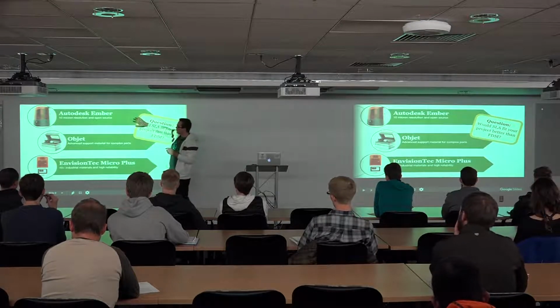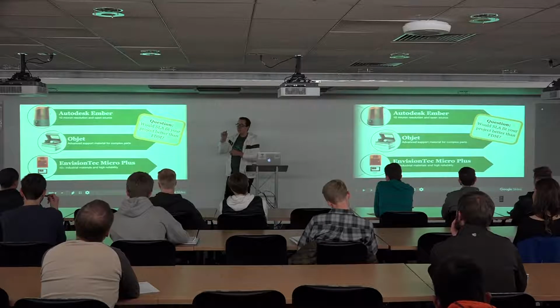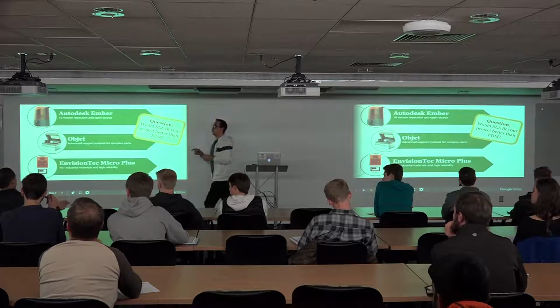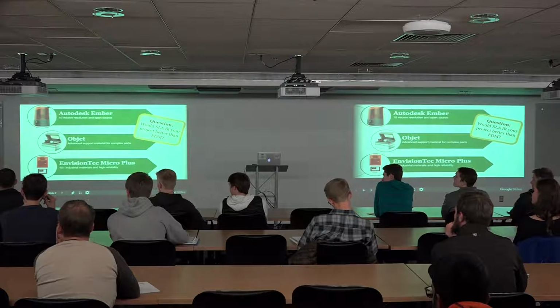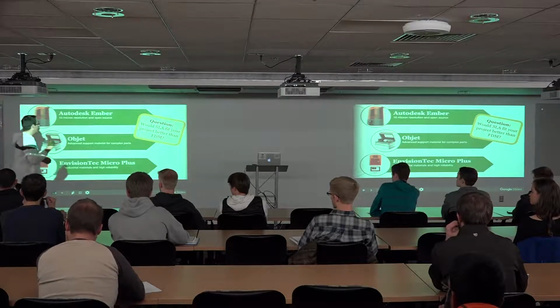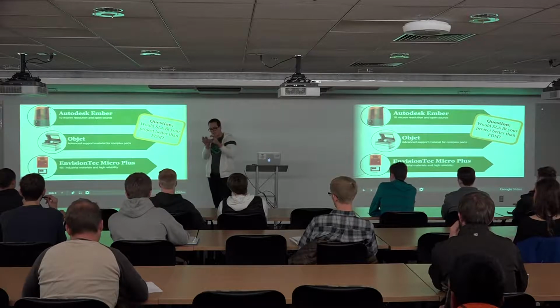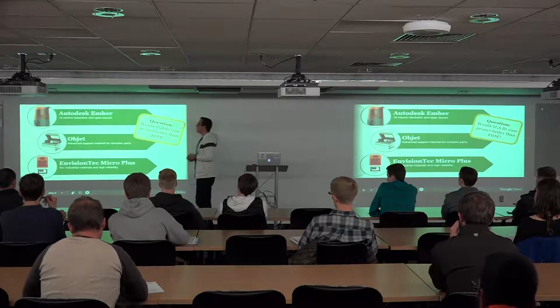So the Ember is also an open source printer, which is really cool. And it prints down to 10 micron layer thickness, so you can get some really, really neat detail. Did you bring any of those parts? Oh, did they pass this one around already? So yeah, this is an SLA version of this, just scaled way down so you can see some of the detail that you can get there. But yeah, 10 micron resolution, you can print really, really tiny things. It doesn't have a huge build volume because of that. You can print parts about this big, rectangular. But if they have to be really fine, then you can get the detail there.